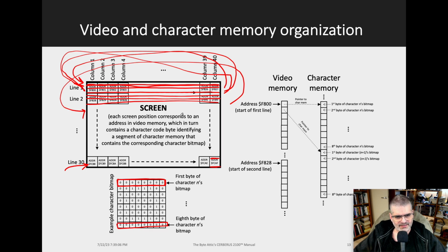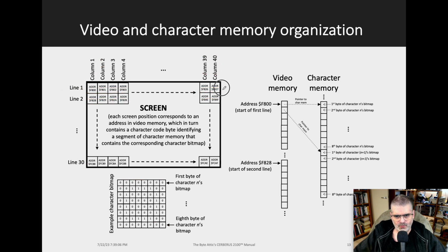Now, to complicate it a little bit more, you would think, well, we have to return to a single row of characters 8 times because each character has 8 bytes. But I'm going to double sample each of these rows in order to fill the screen while keeping the resolution within limits, because dual-ported memories are very expensive. So I'm going to return not 8 times, but 16 times.